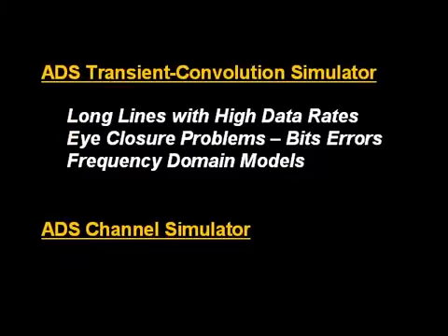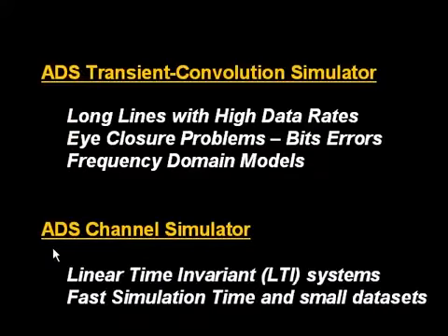I'll be using a frequency domain model. And then for the channel simulator, which is only used with linear time invariant systems, I'll show you how to set that up and also tune with a couple of taps. It's a fast simulation and small data sets are the result. For transient, you save a lot of data, but not with the channel simulator.